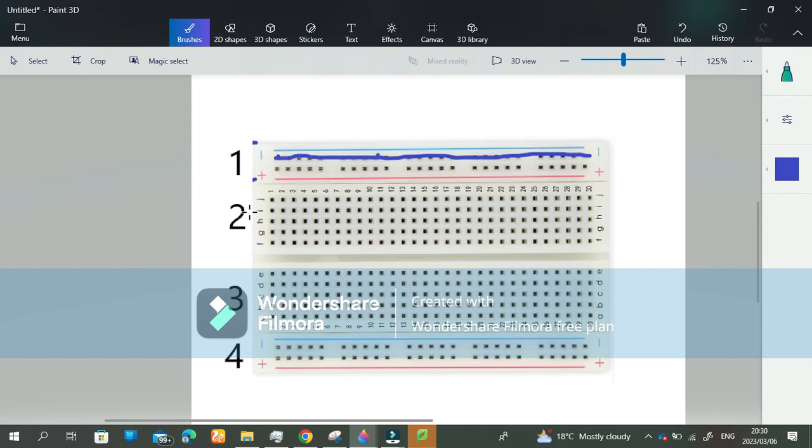Now, moving on to the second section, these ones are connected slightly differently from section 1 in that the terminals that are connected in series are vertical instead of horizontal. The horizontal terminals are completely isolated from each other, meaning that there is no connection underneath, as you can see from my drawings. However, as I mentioned before, sections 2 and 3 are completely isolated from each other, meaning that in the middle of these 2 sections there is a break. Therefore, there is no connection. And section 4 basically operates the same as section 1 with regards to the horizontal lines being connected in series.